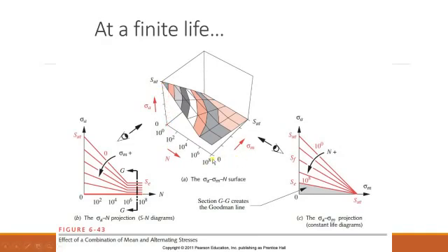Looking from this direction, if I'm all the way out at infinite life, or at 5 times 10 to the 8th, or the farthest out as I can go, this is where I got my numbers for the modified Goodman graph. And what we see is that as we do any cross section, at any given sigma m, there exist two sets of curves.